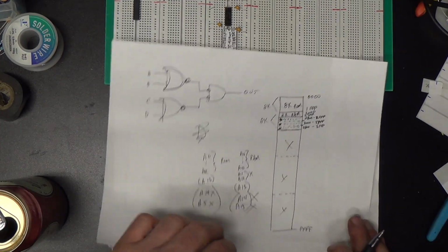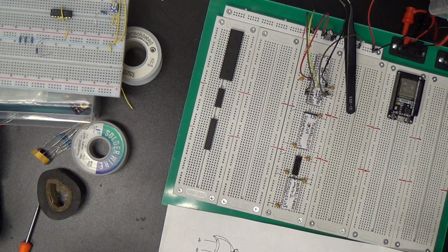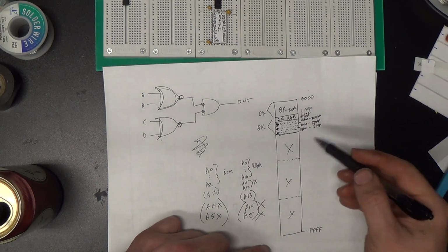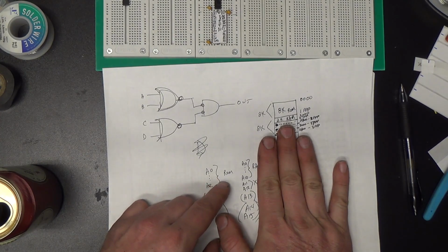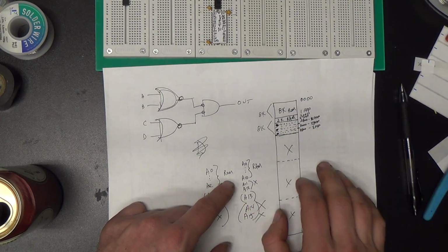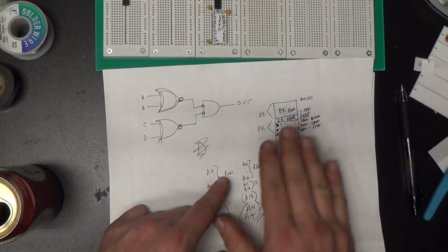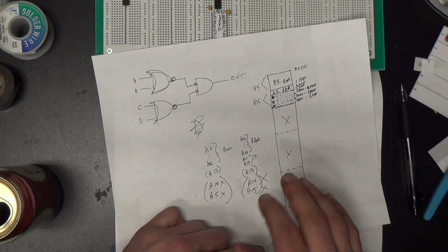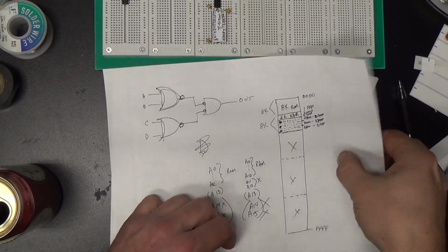Since this is just a breadboard computer that we're not going to be making expansion cards for, it doesn't matter that all of this mirroring is going on, as long as we inform our compiler or assembler to only use that first 8K segment and the 2K segment immediately following it. This first 10K segment, we should say, our code will work just fine. So this is what the memory map of our initial excursion into the Z80 is going to look like.